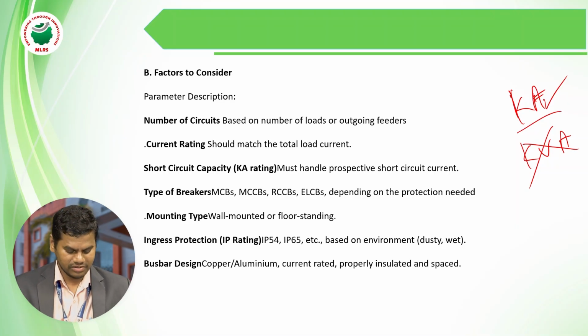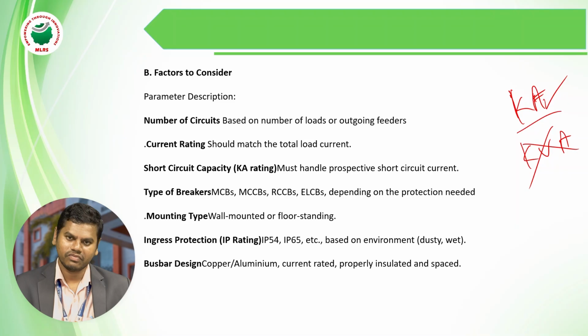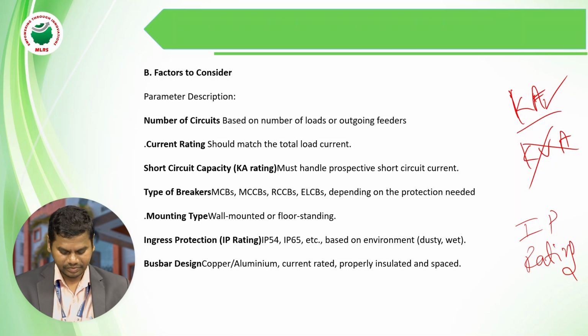Next, mounting type. Here in the mounting type, it is either wall mounted or floor standing mounted. Ingress protection is nothing but the IP rating, like IP54 and IP65, etc., based on the environment, whether it is dusty or wet.